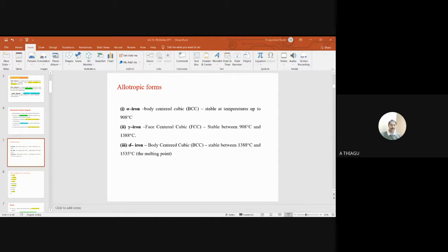Please remember the reaction. This is where we find the low temperature, I already said 727 degrees centigrade. Gamma is going to produce alpha and cementite, so S equal to S1 plus S2. This is the reaction. I hope you are already familiar with these terms: reaction, temperature, and phases. Phases means ferrite, austenite, cementite, pearlite.